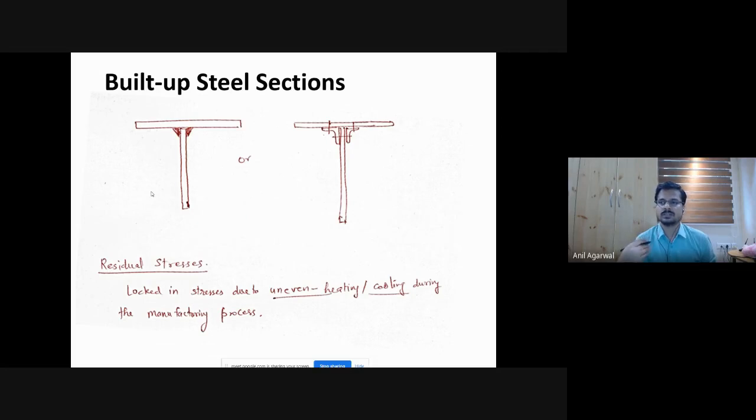And when the residual stresses become that high, that becomes a major concern when you design. Okay, because you are almost already at 70% of the yield capacity. What more can you use? You can use only 30% more, right? So that becomes a concern, and there are ways to release those stresses, especially after welding. I'm not going to go into that one. If you want to take some courses on fabrication, maybe in the materials or mechanical engineering, there you may find more details.